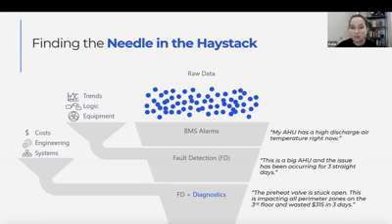I actually know it's the preheat valve because I know my logic, I have some engineering, I know what type of equipment I have, and it's impacting the perimeter zones only on the 3rd floor, and it wasted $315 in 3 days. So it's really taking that extra bit of information, giving your technician even more information at their fingertips to decide whether they need to act. And when they act, they know what to do without spending a lot of time doing the research.